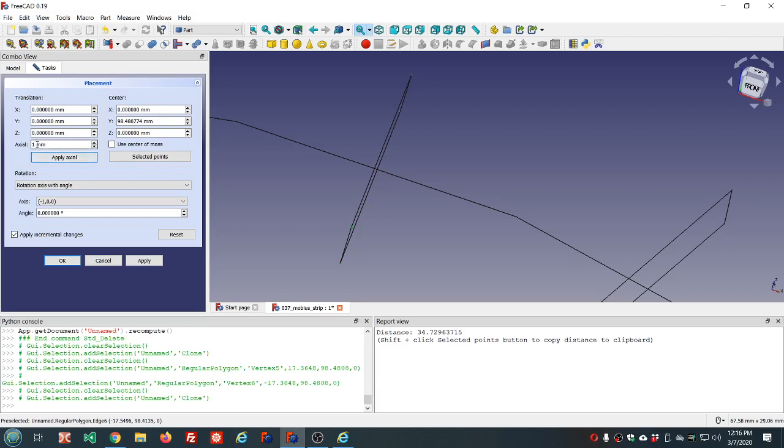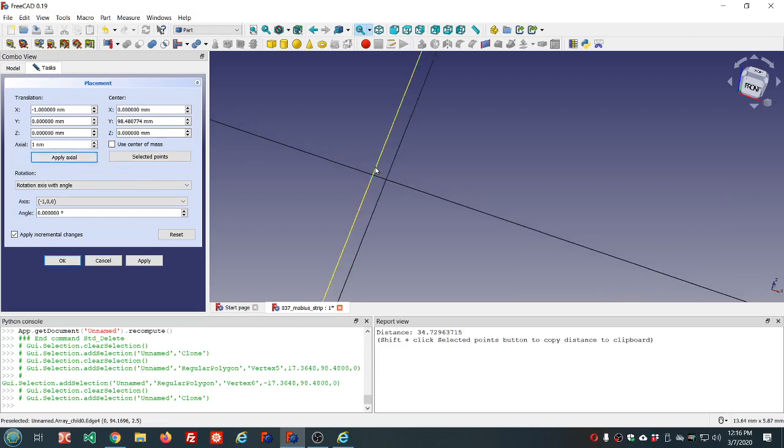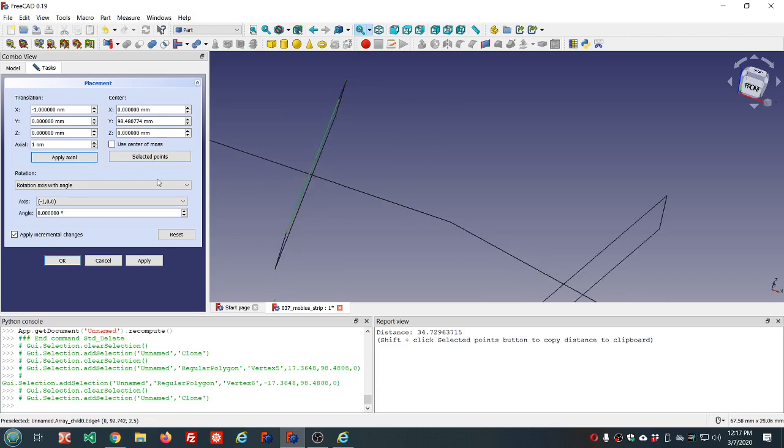But I only want to go 1 nanometer, not a full millimeter. So we zoom in. You see that I've moved it by 1 nanometer. It keeps flipping sides on me. Did I go in the right direction is what I'm asking myself now. And change this to M just to make sure. No, I went the wrong way. That needs to be positive, but only 1 nanometer.